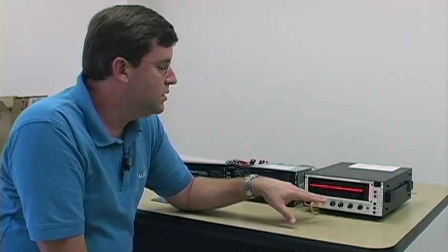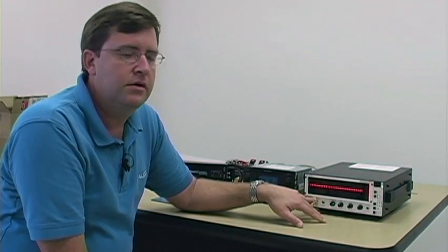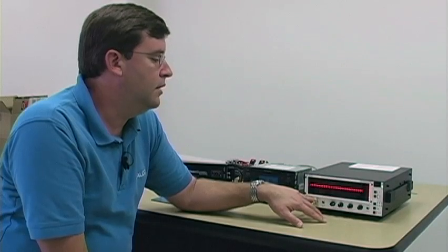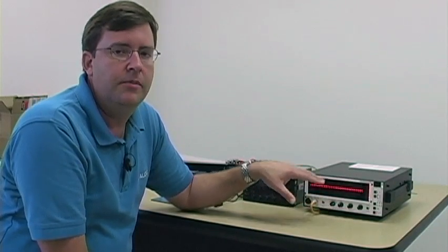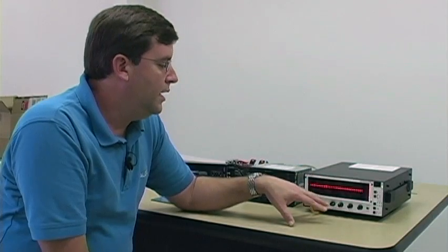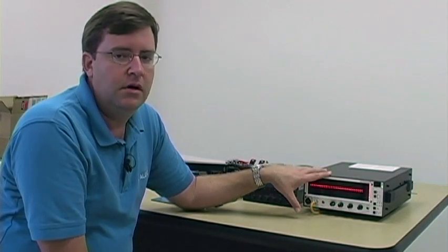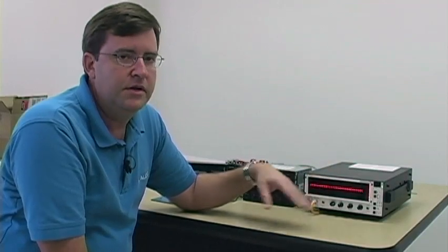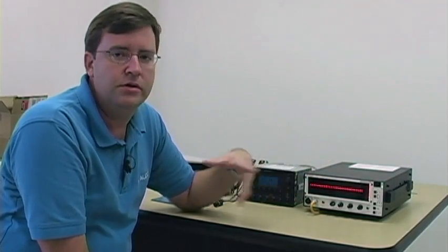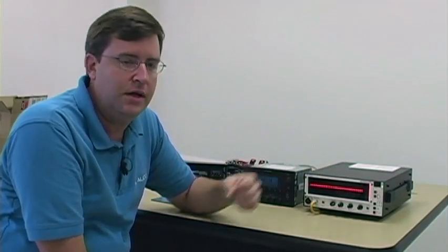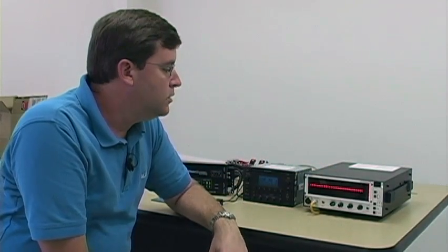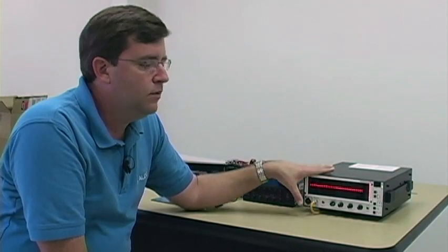What we're using here is the line level input of the RTA. So all we're looking at is the frequency content of the electrical signal coming out of the source unit. We're not interested in the acoustic response of the car. The acoustic response is going to vary from this depending on your speakers and locations and your gains and your EQ settings after the fact, etc. So we're really just looking at the starting frequency response of the signal that we're working with in the system.